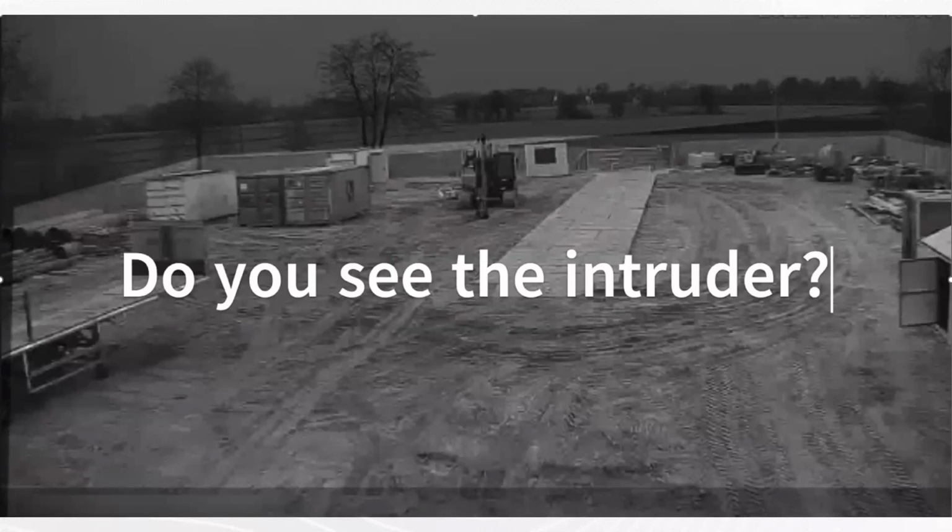As you can see here, the distance to this gate is around 97 meters. And take a look at this. This is what the camera actually sees. As you can see here, we can see only the legs of a person. Why? Because of the H.264 compression, the most typical compression that you have in cameras. H.264 compression will eat some of the details, right? The compression will think, okay, this is just noise, so we need to compress it. And because the color of this person's jacket was similar to the gate, the compression just ate all the details of the jacket and only left the legs of a person.